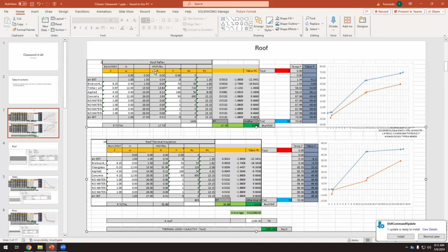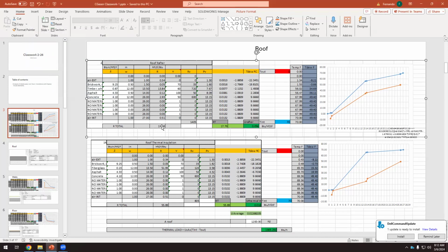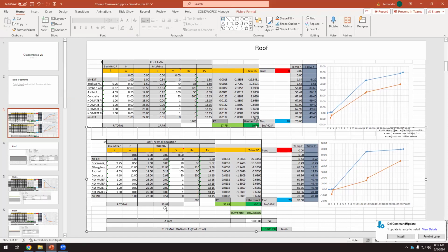We have this thermal insulation or the R value through the rafter. It's a little low, but this is good enough. Okay, so the average is 45. How can we fix this? Increasing the thermal insulation. So if we just go to the thermal insulating material, here we have fiberglass. So if instead of 12 inches, we have more, we will increase this. Okay, so the more, the better.